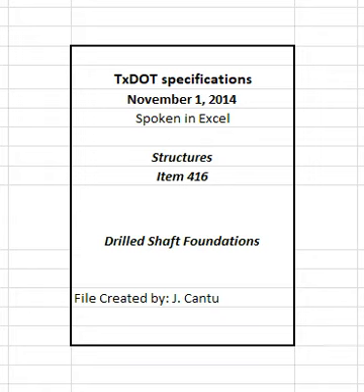Table 1. Concrete for drilled shafts. Drilled shaft type and concrete. Non-reinforced has a concrete classification of Class A. Reinforced has a concrete classification of Class C. Slurry and underwater concrete placement has a concrete classification of Class SS.